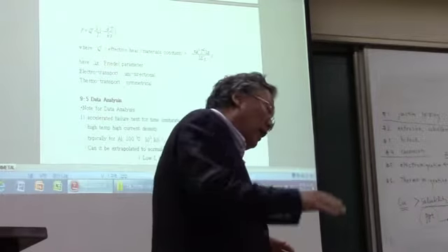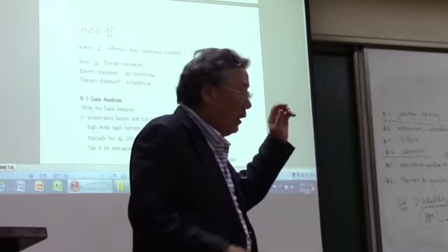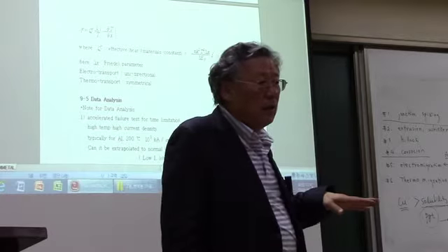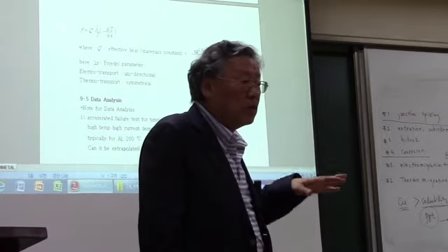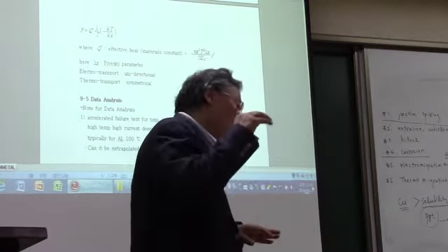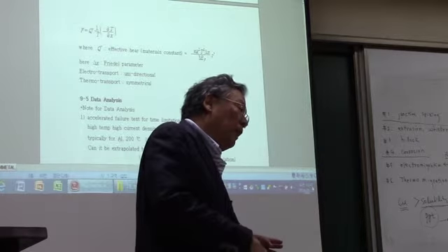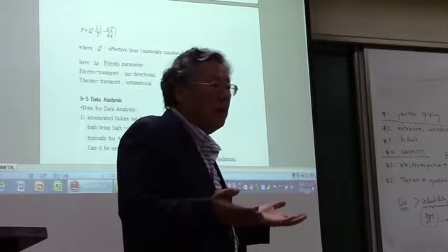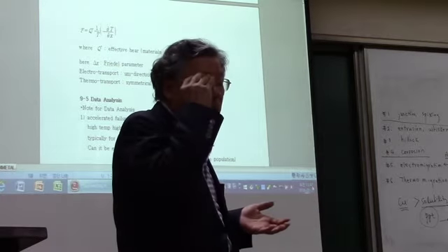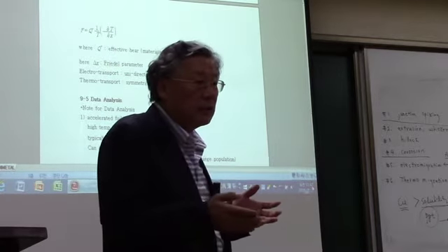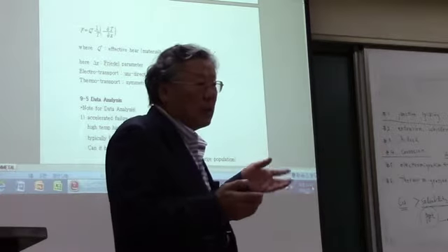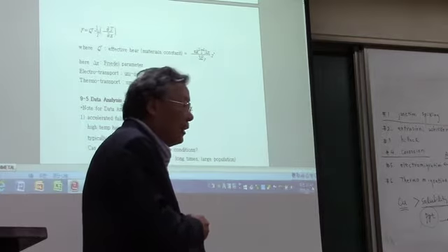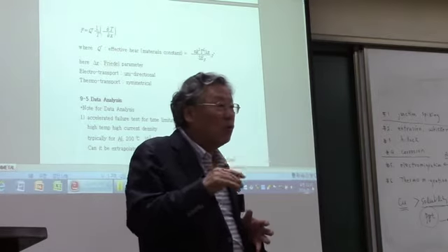before you put the metal lines, your substrate on the contact side has the source and drains, which are heavily doped silicon, and the metal lines on top of the gate, that is polysilicon, not single crystal silicon, and the metal lines running over the field oxide, that is on top of the SiO2.